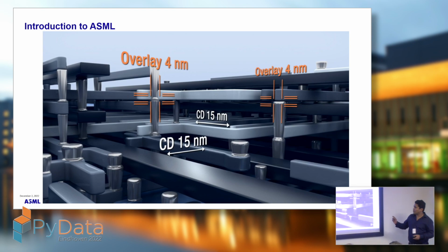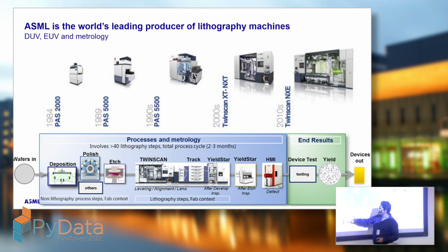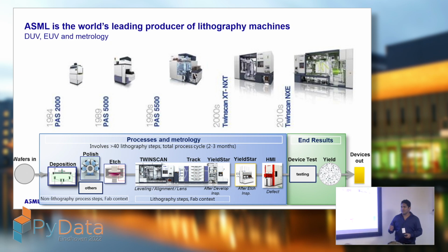This is the feature we are talking about. This is imaging, purely what we do. This is the hardware printing we do at ASML. Now, again, zoom out a bit. Started in 1984, now almost 2023. At that time, when we started imaging with our past 2000, the resolution was at micrometer level. Our hair is around 50 microns. The resolution was around 1 or 2 micrometers. Here now we are talking about 14 nanometers, 13.5 nanometers. So that's the improvement that imaging went through.